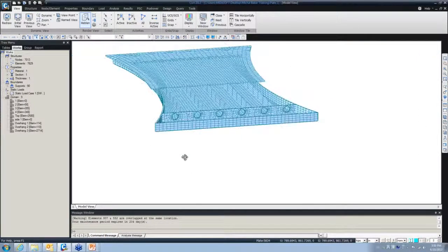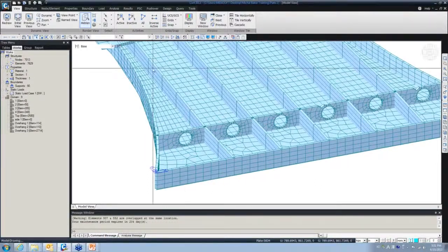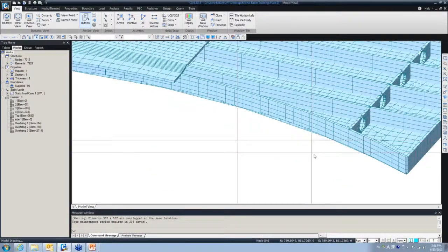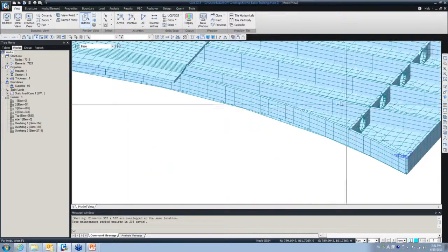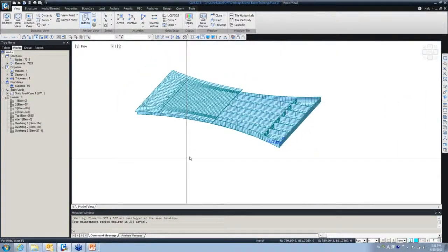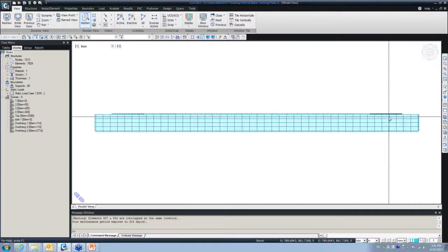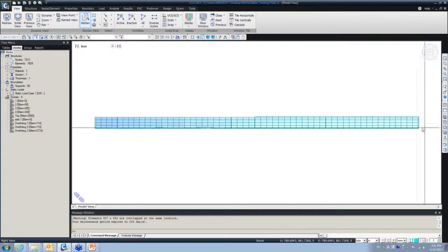So I'm going to show you the workaround. For example, if you have this plate and you want to post tension this element, you just define a beam in the middle of this slab right here. It could be on a curve or on a straight element, it doesn't matter. Then we can post tension that beam element. There should be some assumptions and simplifications to ensure that everything goes smoothly and comes up with the correct result that we are looking for.